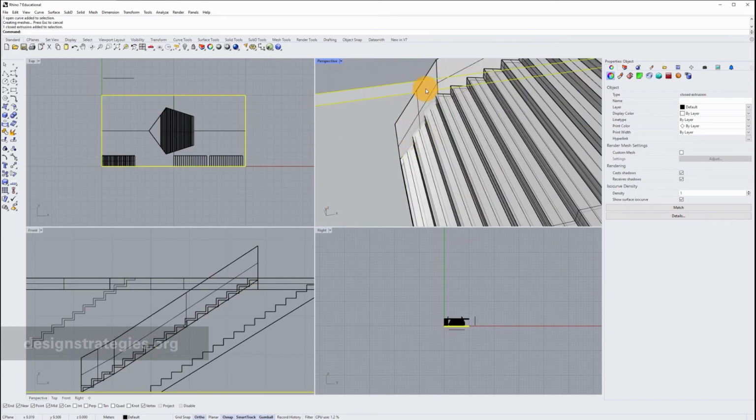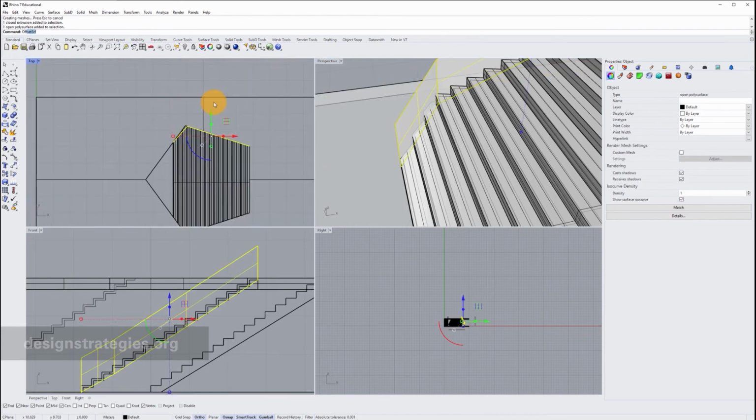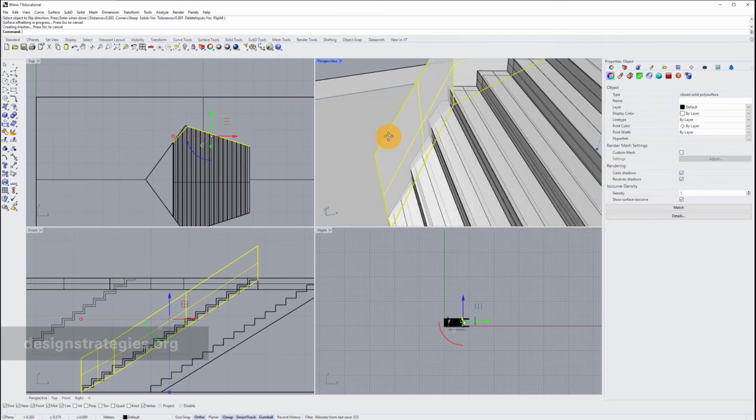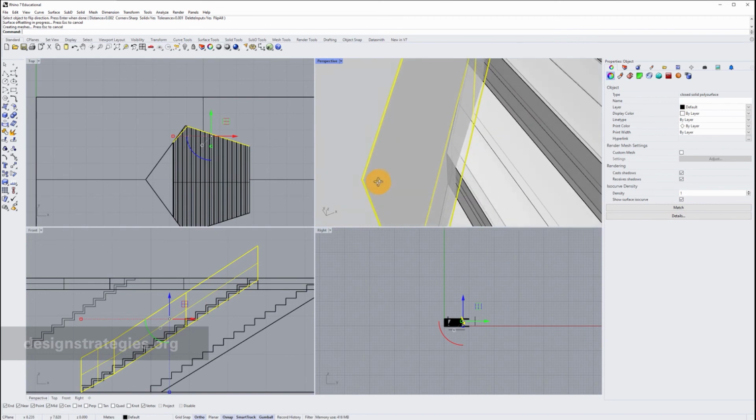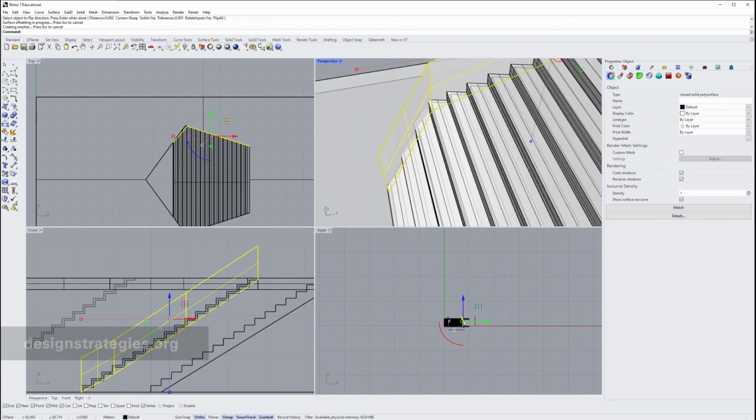And then I take the surface and I just create an offset surface, and just have to see in which direction. Yes, and the surface probably gets a dimension of 0.02 centimeters. And this, for example, could then be a glass banister if I just give this the material glass.